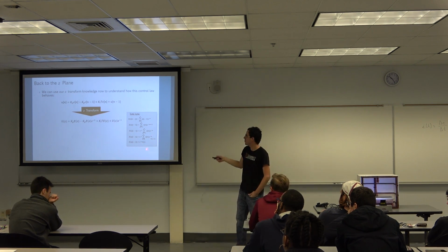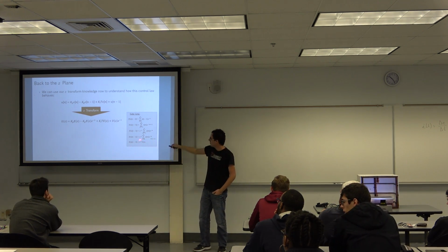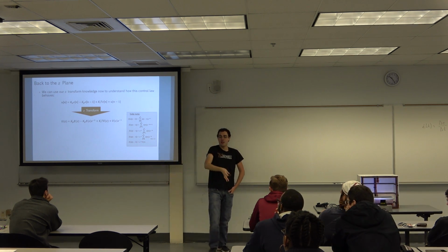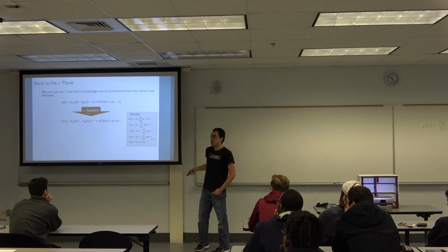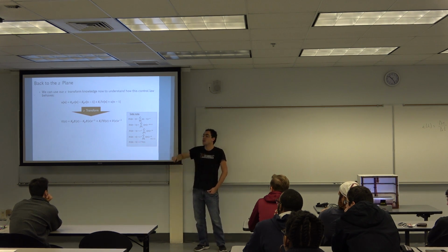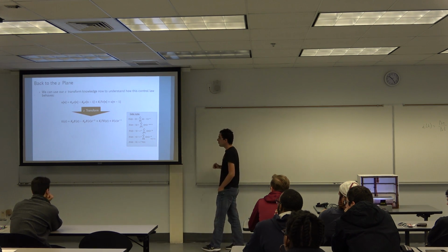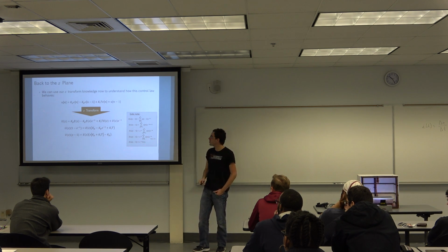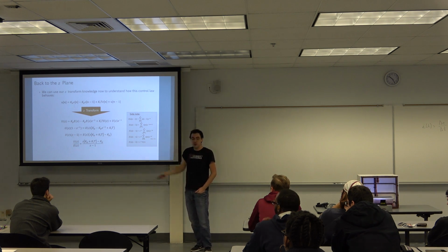I might place this in the lecture notes if you want to understand what's going on over here. But this exponent minus 1 can be minus n for the nth past sample. So if you have 5 samples behind, it would be z to the minus 5. If you have samples in the future, you just replace this with z to the positive 1, and then you get the future 1 sample. Okay, so we do that. We do some mathematical handling of this expression, and we come up with a transfer function very similar to what we do in the Laplace domain.